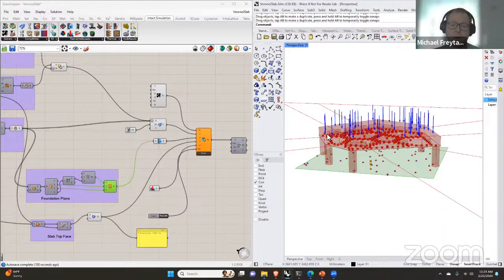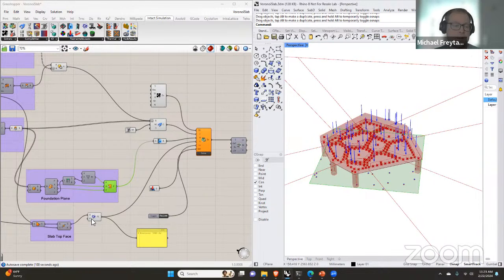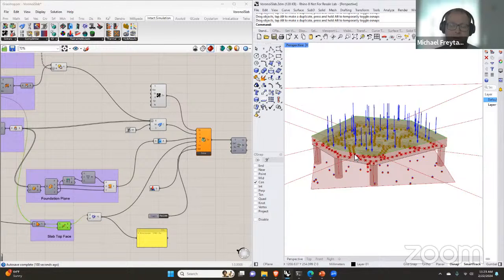We've also got a pressure load applied to the top face. I preview that to this top face; this stuff is all parametrically done through Grasshopper. And this is a pressure load of 5,000 pascals, 5,000 pascals applied over that top surface. And we also have a gravity load.